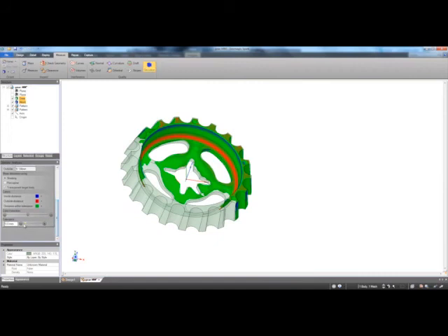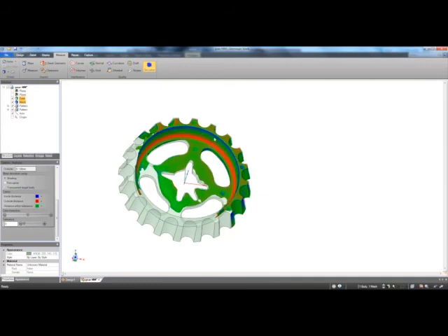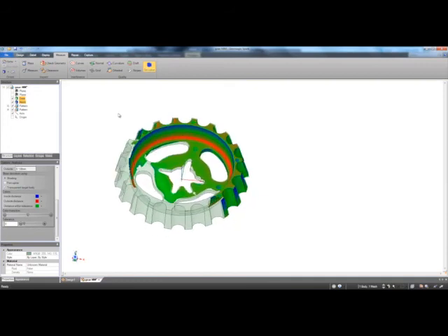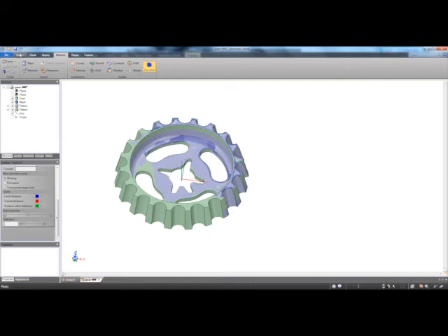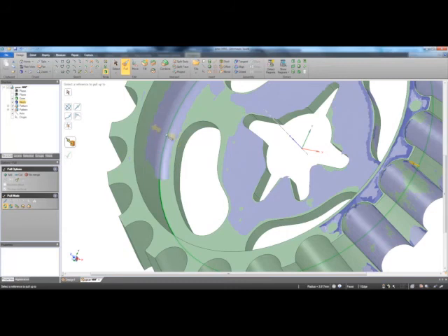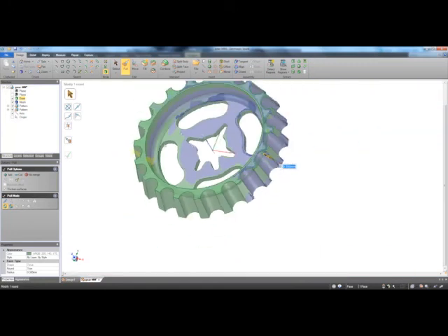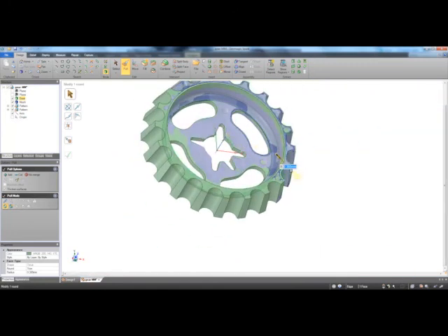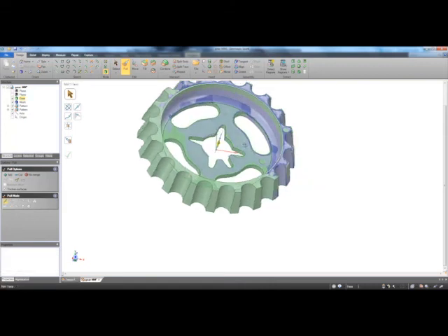And then on the left hand side, I can adjust my tolerance settings as well with this little slider. But let's just say I want to make that round. I just left mouse button in the graphics. It gets me out of deviation mode. Go back to design. I can choose pull. I can choose this edge, and I can say pull that up to, I can choose this rounded part of the mesh. Pull that round to that part of the mesh, which is kind of nice. I don't have to worry about what the value is or try to guess. And I can fine tune it again to what it might be, just rounding it off a little bit.